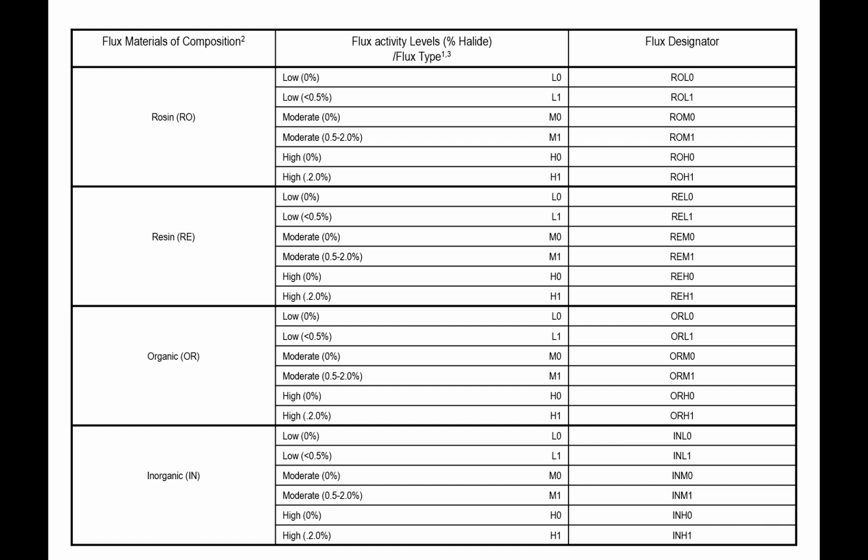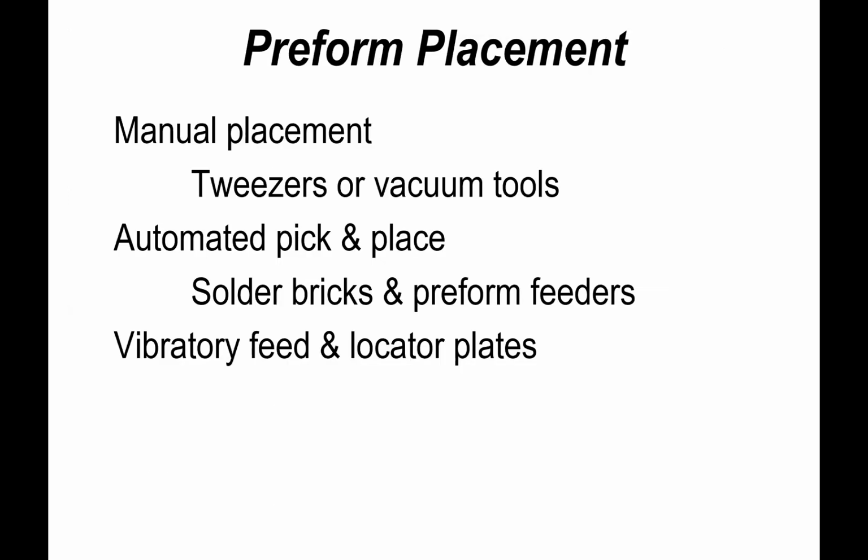And we're talking about very small percentages of flux, certainly nothing like when we consider the amount of flux or flux vehicle that's present in a solder paste. So the actual residues left behind are fairly minimal in most material cases. But again, that's something you speak to your supplier about and evaluate it for its cleaning and cleaning potential.